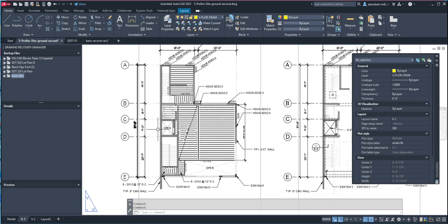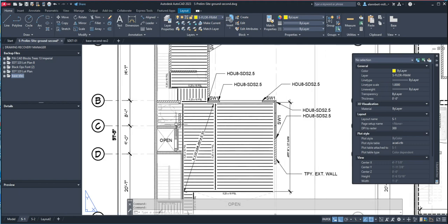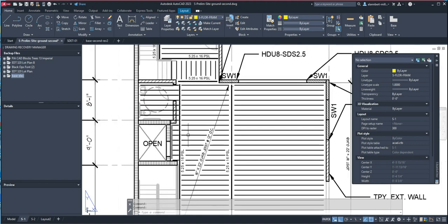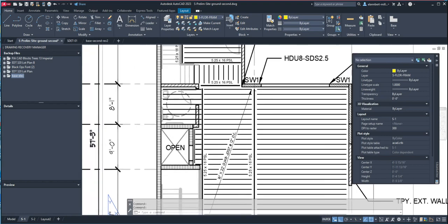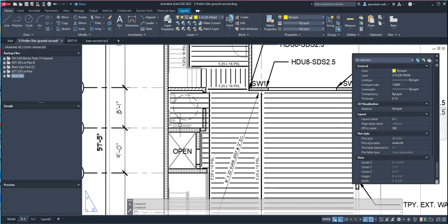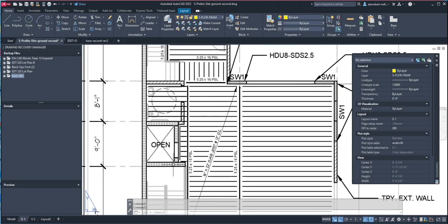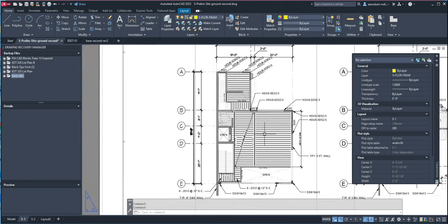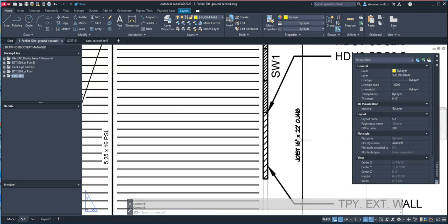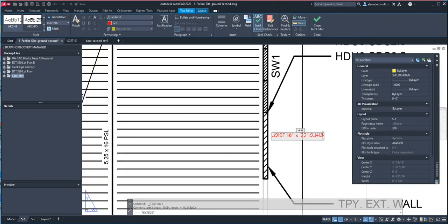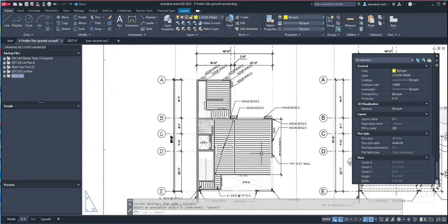There you go. And then this one here, if it's the same joist, then you call it out too. Actually, it's from here. So we're just gonna do it the way we did here. We didn't also call out the spacing here, so I'm gonna add the spacing here at the end. At 12 inches OC. Okay, and then we'll do the same thing here.